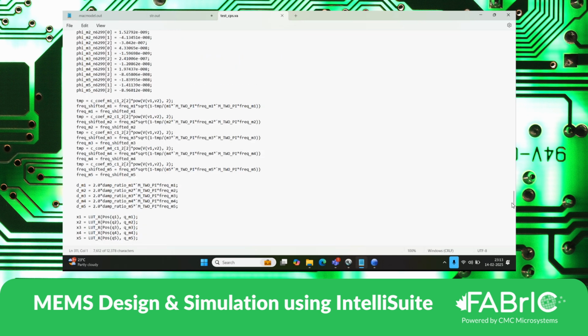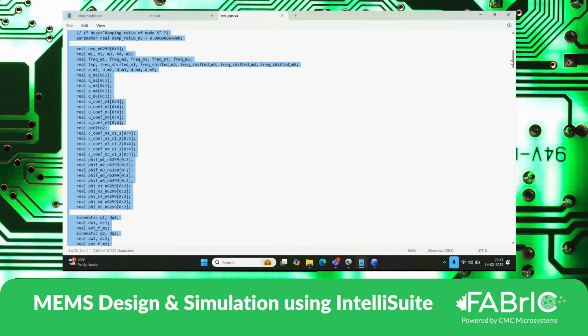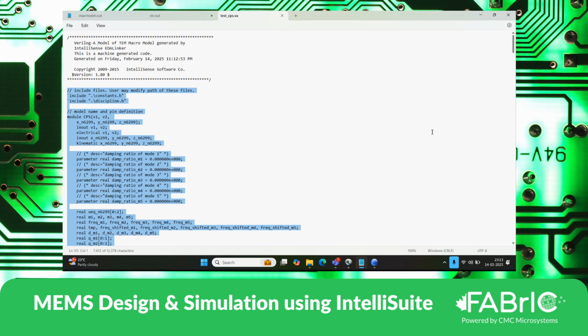Okay, so what we do here, since I do not have access to Cadence or Synopsys, what I've learned from users is that in the case of Verilog, we open Cadence Virtuoso and then create an empty file and then paste this code into that empty file, and then a template gets created in Cadence Virtuoso, and further the integration with IC can happen.